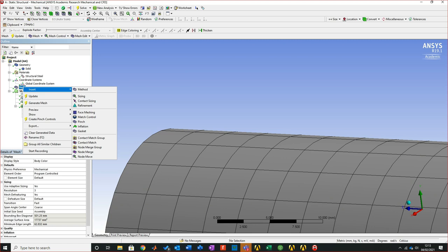Now, I know some of you have already looked at meshing before with Akinola, but what I'm going to do is not CFD meshing. So I know a lot of people go, well, why don't you just use the inflation meshing? In solid mechanics, it doesn't work as nicely as you'd like it to. Inflation meshing on something like a flow is absolute golden. It's brilliant. But with the solid mechanics side, it's a bit glitchy and a bit of a nightmare, I should say. I can do face meshing.